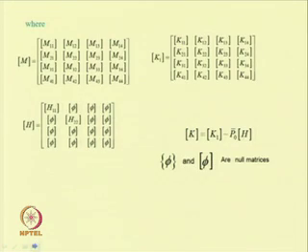So, here this M can be written in this form. One can write M 11, M 12, M 13, M 14, M 21, M 22, M 23, M 24, and so on. These correspond to W t, W b, U t and U b. That means W t double dot terms will be multiplied with this, and W b double dot, U t double dot and U b double dot terms. In that way each submatrix will be of size n by n, depending on the number of modes we have taken, so each submatrix can be determined.